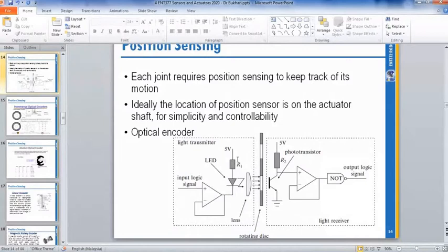If you don't put the resistor, the full current will go through the LED and the LED will burn first. So you don't have a short circuit, but you have an open circuit because your LED burned. This one, because the phototransistor can pass a big current, you will have a short circuit.